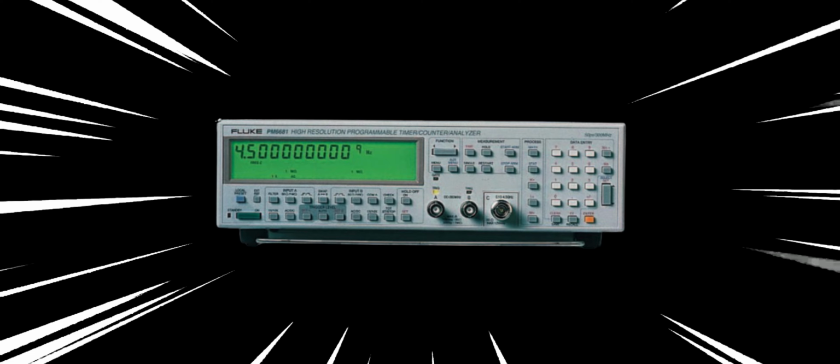This unusual design uses pulse width modulation, a PWM DAC. The on-time of a fixed frequency square wave is varied in discrete steps, producing a waveform with an average voltage proportional to the duty cycle, which is just the on-time divided by the period of the square wave. What's more, the edges of the generated PWM signal can be made very accurate.